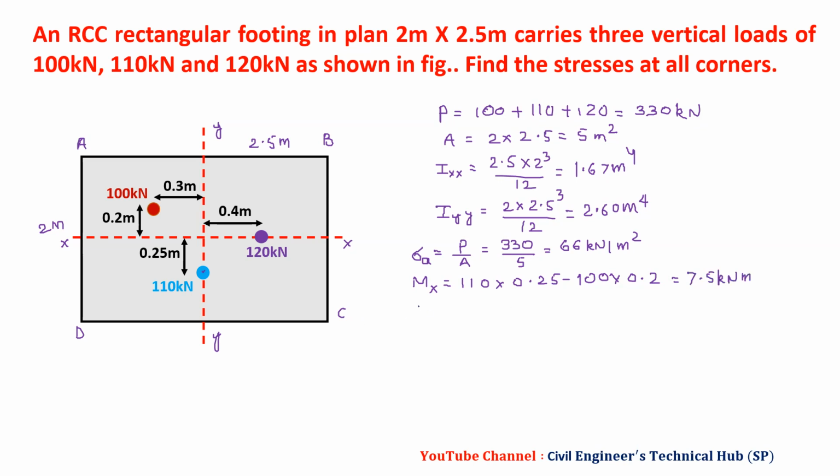Then, since the moment about y, My, is due to 120 which is larger than 100, we have 120 into 0.4 minus 100 into 0.3, and we get this value, 18 kilonewton meter.